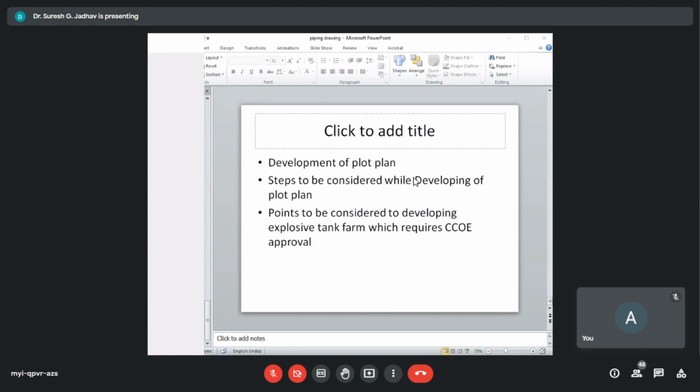Depending upon the regulation governing the area and type of industry. Then, area reserved for tree plantation shall be one third of the area occupied. Parking space is 10% of the plot area. Water storage capacity is 24 hours minimum. Then we have to consider some basic points that can be used to estimate the water requirements. Domestic water is 100 liters per person per day.